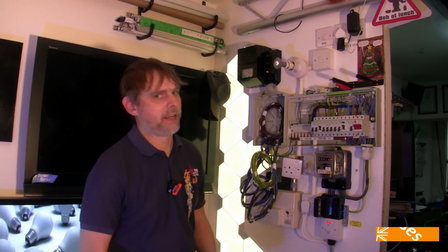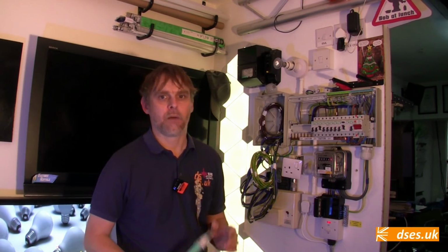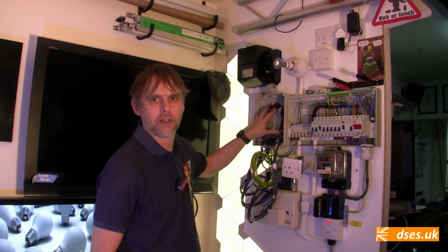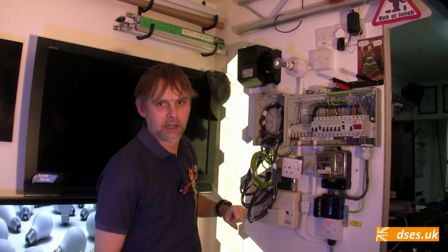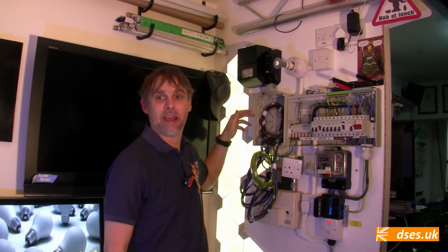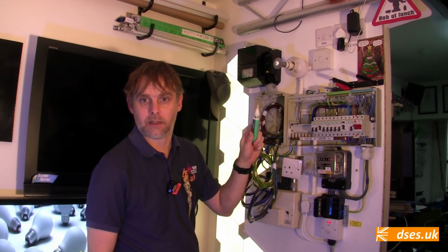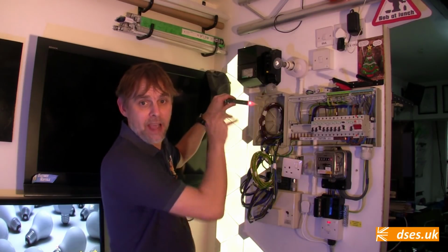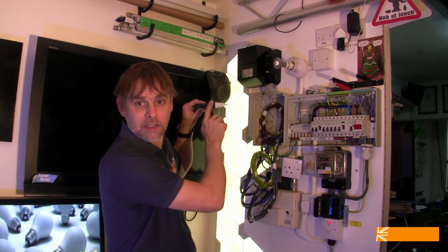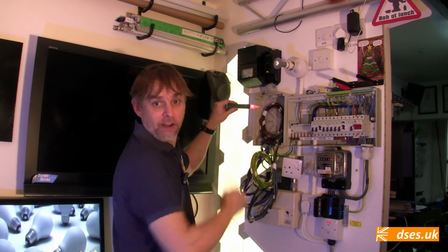So how do the basics of a capacitor apply here? Well, I said that a capacitor is two conductive plates separated by an insulator, and what we happen to have here is an energised copper conductor on the 2.5mm socket wire, a dielectric insulator formed by the PVC insulation and an air gap, and a conductive antenna in the tip of the non-contact voltage indicator. We have therefore created a capacitor between the energised wire and the non-contact indicator, and a tiny current can pass through the electric field of that capacitor.